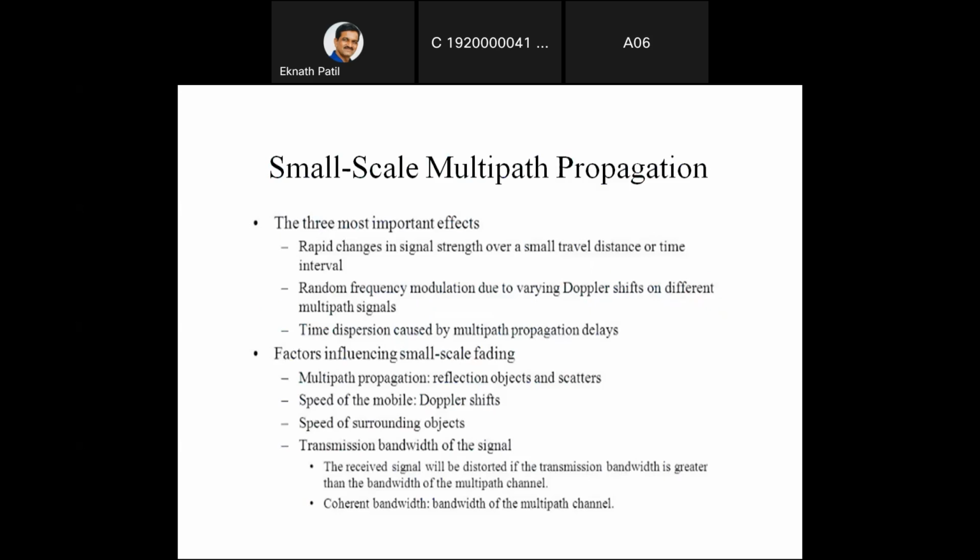That is the first part of the multipath propagation. Second is random frequency modulation due to varying Doppler shifts on the different multipath signals. Third, time dispersion caused by the multipath propagation delays. These are the three main important effects.